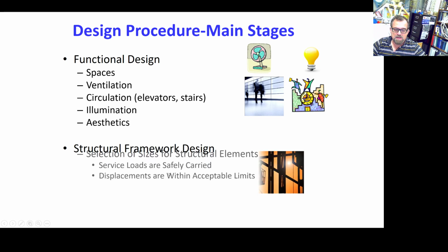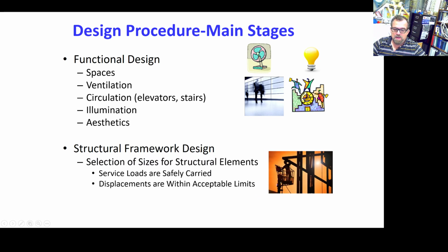Now the structural framework design, basically what it is is selection of sizes, materials, type of elements in order for the service loads to be safely carried, the displacement within acceptable limits, and when the structure is functioning also, all the live loads or all the loads that are going to be applied to that structure, either by use, occupancy, or by environmental conditions, are satisfied.